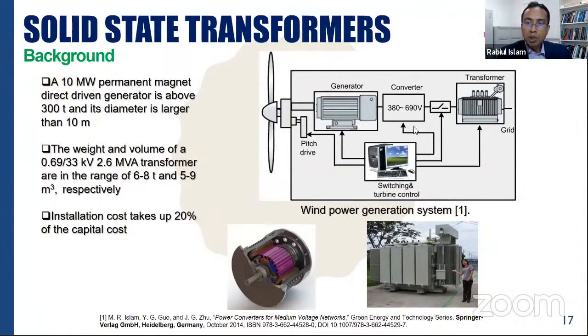So this rectifier and inverter is a low voltage rated traditional two-level converter topology, just like an H-bridge type of concept. That's why we can't go beyond this voltage level, or we can develop a medium voltage level converter with this type of topology. So that's why now we are proposing a new type of converter here, such that we can generate medium voltage or even high voltage through this converter without using a step-up transformer.